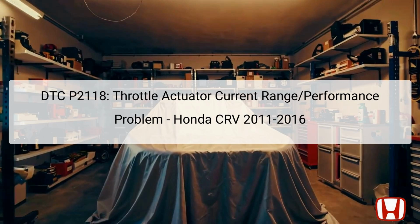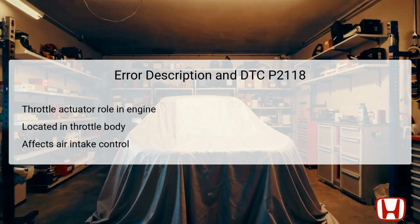The throttle actuator is an essential component located within the throttle body assembly. It controls the amount of air entering the engine, which subsequently governs engine power and efficiency. Therefore, addressing this code is paramount to ensure optimal performance and safety while driving. In this presentation, we'll explore the various aspects of this error code, starting with a detailed description and definition of its components. DTC P2118 signifies a throttle actuator current range or performance problem.